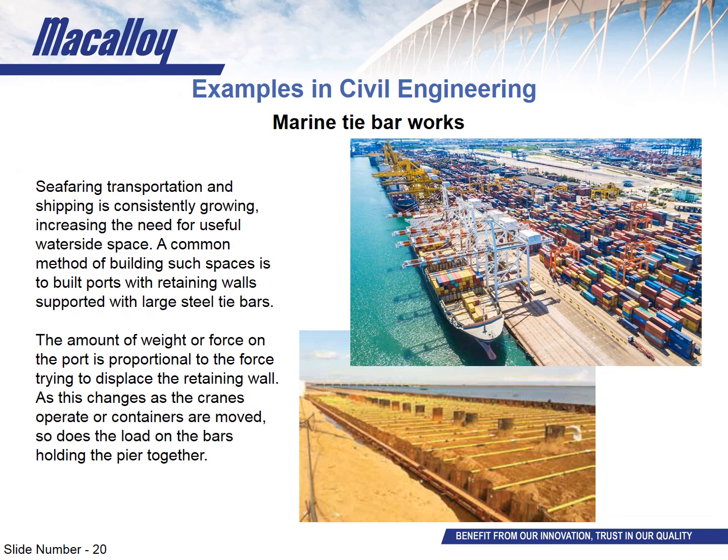In marine tie bar applications, there is not often significant preload, so ensuring the absence of bending moments is a priority. The use of articulation joints in the body of the bar and spherical nuts and washers at the ends gives the bars the greatest capacity and minimises fatigue demands.